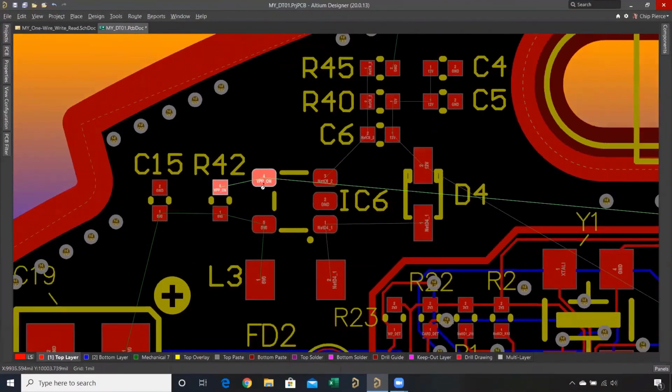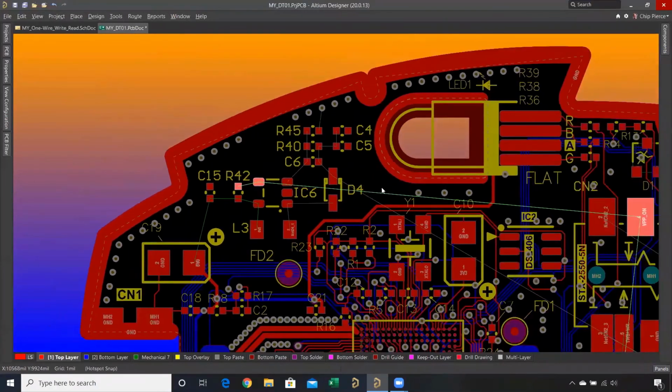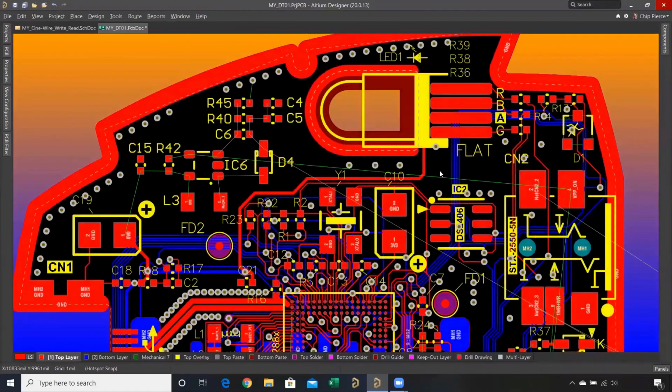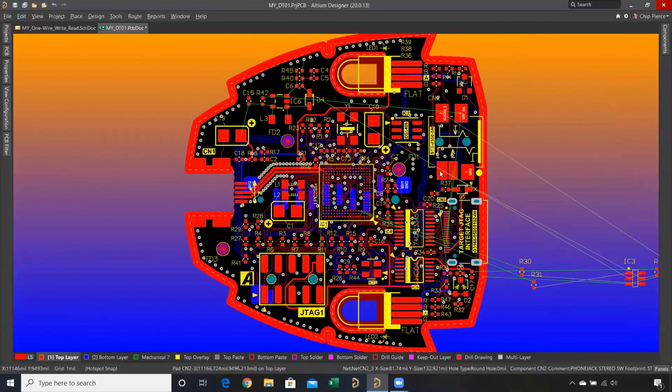And it's going way over on the other side of the PCB. So I would expect that I'm going to probably have to drop a via or two to make that connection eventually, unless I wanted to do some rerouting and get some of these traces out of the way there. All right, so I'm just going to right click and clear filter, VF, view fit board.